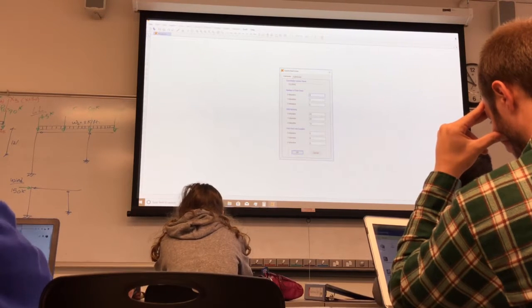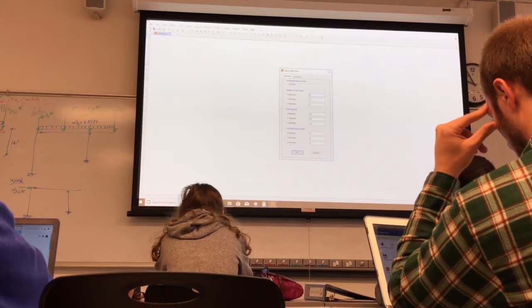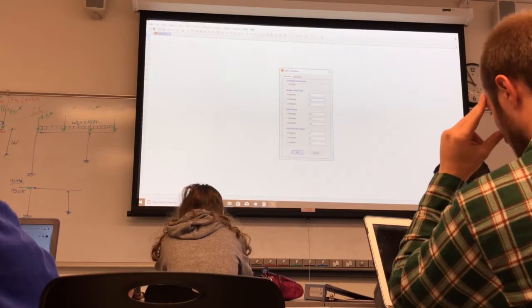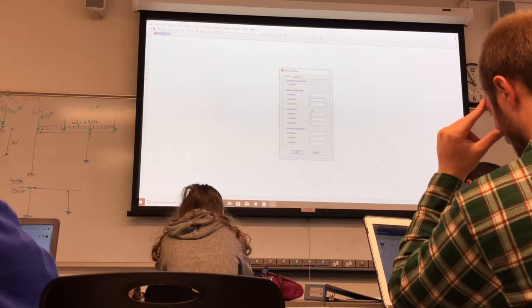Then in Y direction, we don't care about the Y direction because we're doing 2D analysis, right? Y is the out of plane. So we need only 1 grid line. Can't put 0, it has to be 1 grid line because you have a Y1, this plane. That's the Y1. Then in the Z direction, we have 3 as well. So that's gonna be 3 in Z.